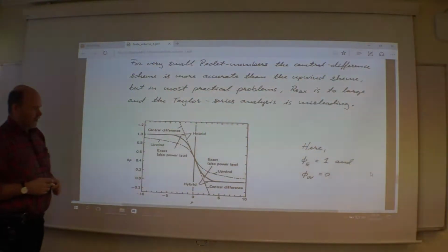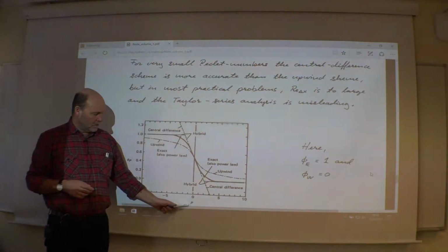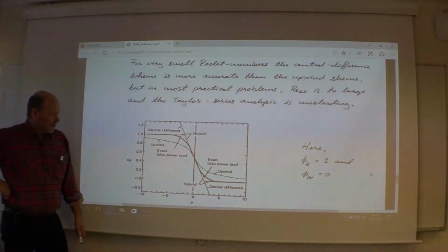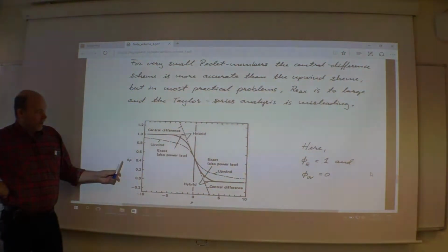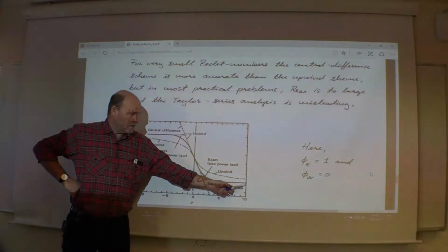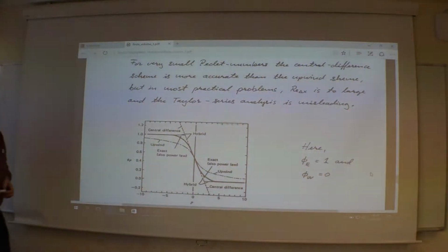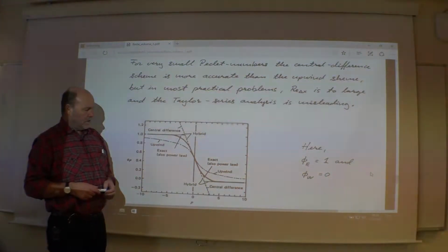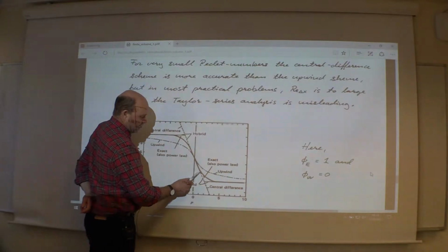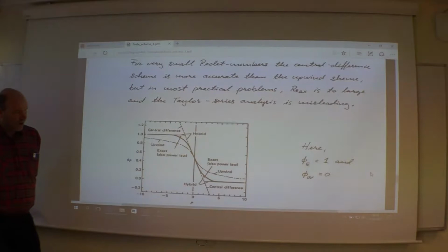Here it's a comparison between different schemes, with different values of the local cell Reynolds number, the Peclet number, and then you have specified the boundary values of 1 and 0. And you have an exact solution for this very simple problem. So it should be nice and smooth, something like this, depending on the Peclet number. We have actually seen this example more or less already.